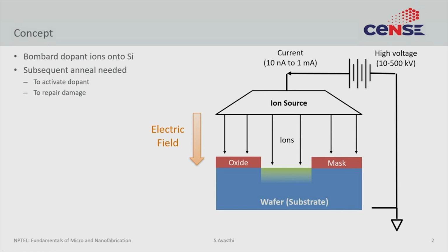You don't just create dopants inside silicon through this methodology, but you also displace the silicon atoms already present in the lattice. And those displaced atoms then need to be put back into their correct position, else you will not retain the properties of silicon. So these two issues, lack of substitutionality and repair, both require anneals. We'll talk about anneals slightly later in the lecture.